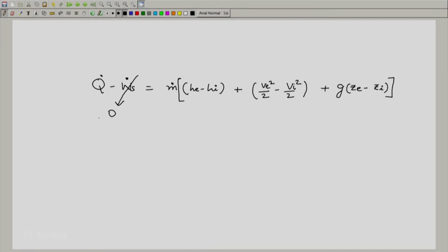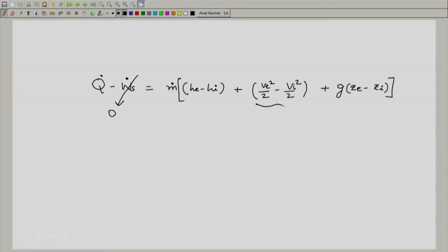What we assume now is that there is negligible change in the kinetic energy. So, even if mass is coming in at a certain rate, the kinetic energy of what is coming in is nearly the same as the kinetic energy of what is going out, and there is not really much difference. This is not a very bad assumption, and hence for our analysis this suits us perfectly. Hence we write this as follows: delta Ek is nearly equal to 0. Similarly, we will write delta Ep is nearly equal to 0.